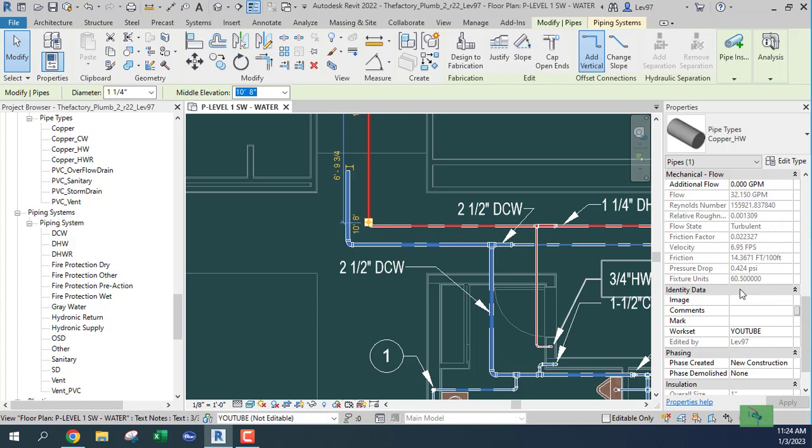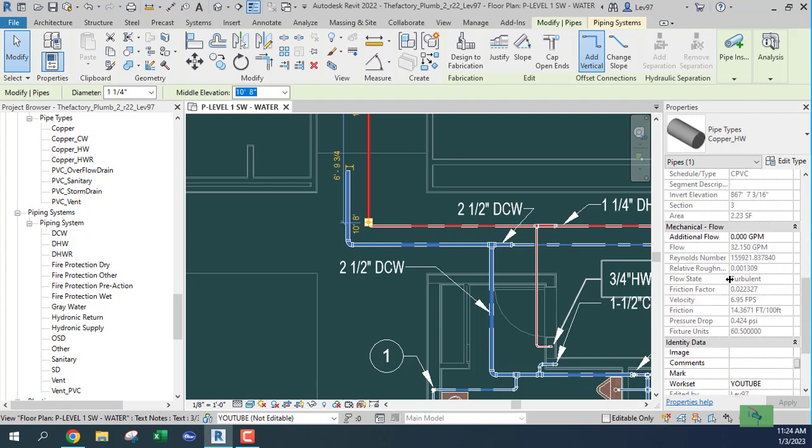If my fixture units in the conversion rate is 60, then according to Hunter curves for flush tanks, the GPM is 32. So it eventually catches up, or it converges to the curve on the Hunter curves somewhere, right?